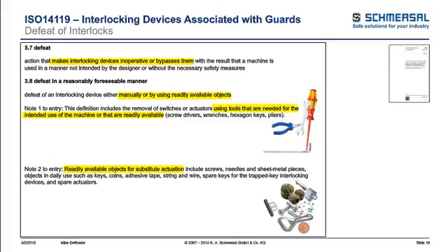One of the most common questions whenever we talk machine safeguarding is the defeat and whether it's considered willful intent if somebody has the tool. If they actually get a tool to remove a safety device, is that not considered willful intent because they got a tool? It's not. And it's, again, highlighted in this standard as well as you see in other standards.